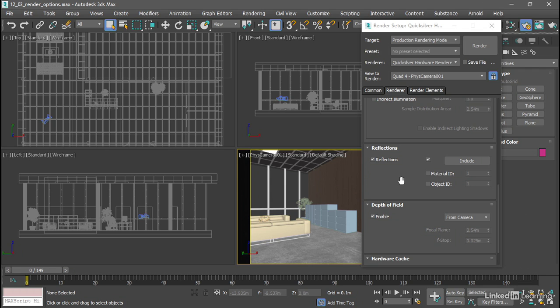But even if these automatic reflection maps gave you good results in your particular scene, for some unknown reason, we do not have the ability to disable reflections from environment while enabling the dynamic reflection maps. Since those reflections from environment are so uncontrollable, we can't have those on. Therefore, we can't use the dynamic reflection mapping anyway. So for an interior, really, our only option is to turn all of these reflections off, meaning we will not get any mirror reflections anywhere in the scene.